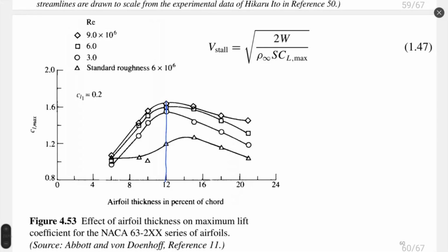Okay, this one close to 12 degrees for an airfoil can be used this thickness as a good value, or let's say, I don't like so much this word good value, because how much is good, everyone decides. It's very subjective definition. But if we see from point of view of lift coefficient, we see that for most cases, 12% of thickness of airfoil is good.